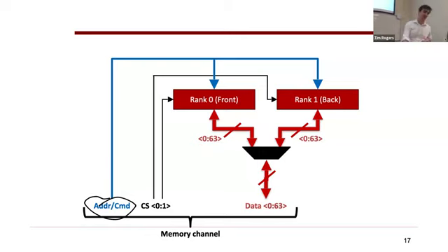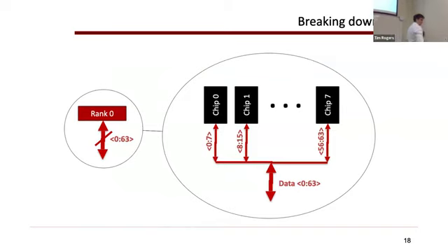And then, of course, we've got the actual business of the bus. So this is the data that's coming back from your chip. In this particular example, we're showing 64 bits of data, but that could be fungible based on whatever the configuration of your memory system is. And as I mentioned before, a rank is like one big logical chip, because we can't actually output, for example, 64 bits from one chip alone. So we would output 8 bits from 8 chips in this example, and then be able to wire that up to the 64-bit data bus that's running between your memory controller and your memory system.